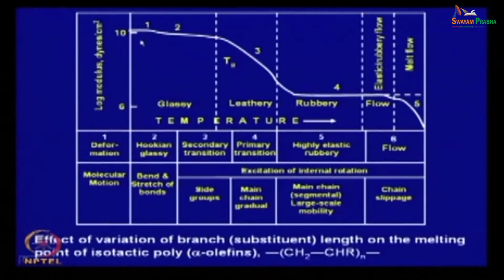And this range of temperature between these phases is a glassy range, then beyond that it becomes flexible, so it is the leathery range, and this transition is the Tg, from where it passes from glassy to leathery range, then from leathery to rubbery, which becomes a little fluid, more fluid than leathery.